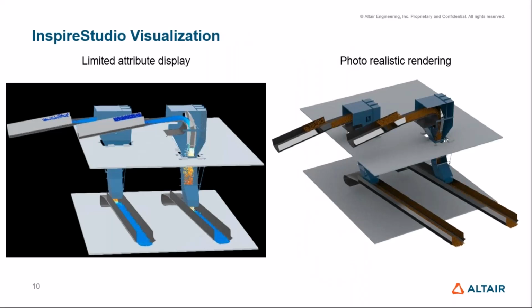At the moment, there's two different things you can get out of it. There would be an option A that's less common, but still something that is currently being worked on and will get additional features: the fact that we have an attribute display. So similar to when we are doing coloring in EDEM, we can actually color the bulk material at the moment as well for a limited range of attributes. So I believe it's velocity and angular velocity at the moment, but that's an option. The other limitation is that it's only available not in the full rendering mode, but in a preview rendering, which is what you can see in the slide on the left.